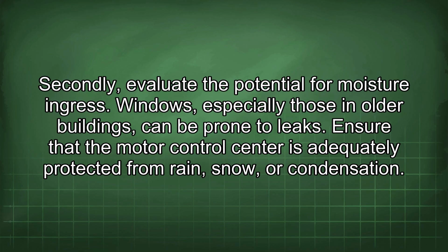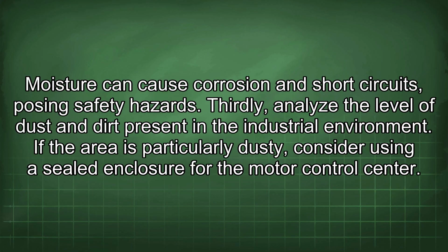Secondly, evaluate the potential for moisture ingress. Windows, especially those in older buildings, can be prone to leaks. Ensure that the motor control center is adequately protected from rain, snow, or condensation. Moisture can cause corrosion and short circuits, posing safety hazards.